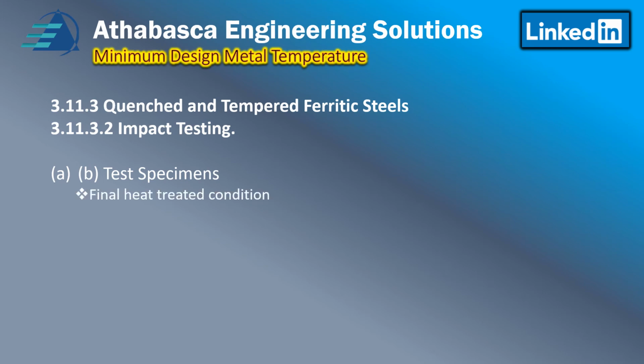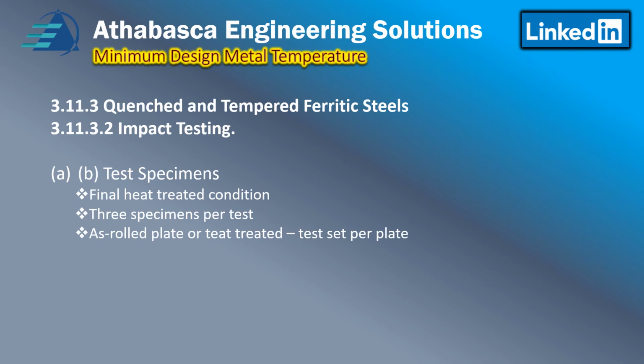In summary, it's the final heat treated condition. Three test specimens per test are required. It has to be as-rolled plate or heat treated plate, and there has to be one test set per plate. For pipe, rolled section forgings and castings, we have to do one test per lot.